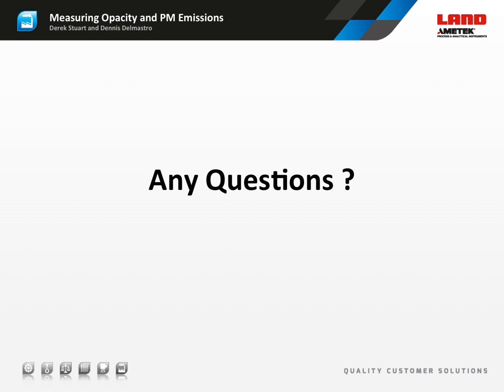Here's another question. To obtain a certified opacity monitor, must the manufacturer conduct any tests? Yes, ASTM D6216 identifies the specific tests that a manufacturer must conduct. These tests include 1) per unit tests, 2) quarterly tests, 3) annual tests, and 4) field audit tests. The purpose of the tests in 1 through 3 are to validate and certify that the opacity monitors being built meet both the design and performance tests. The field audit performance tests validate and certify that the installed monitor meets the proper performance tests.